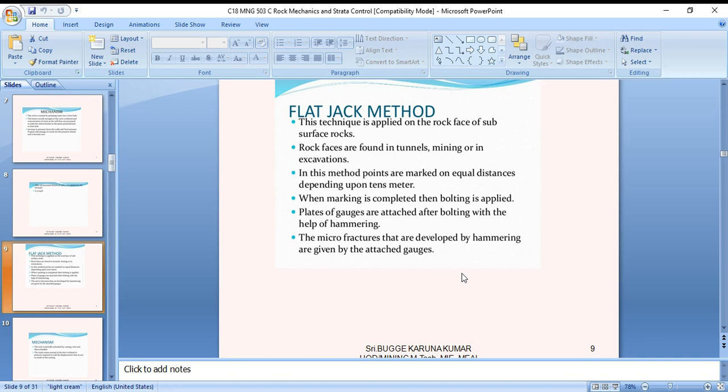Some instruments are calibrated by the manufacturer and come with a calibration certificate. Others, such as a micrometer, are supplied with a secondary standard. Instruments developed in research laboratories are usually calibrated against a primary and secondary standard. The accuracy of an instrument is often expressed as a percentage of the maximum measuring range or some arbitrary value within the measuring range of the instrument.